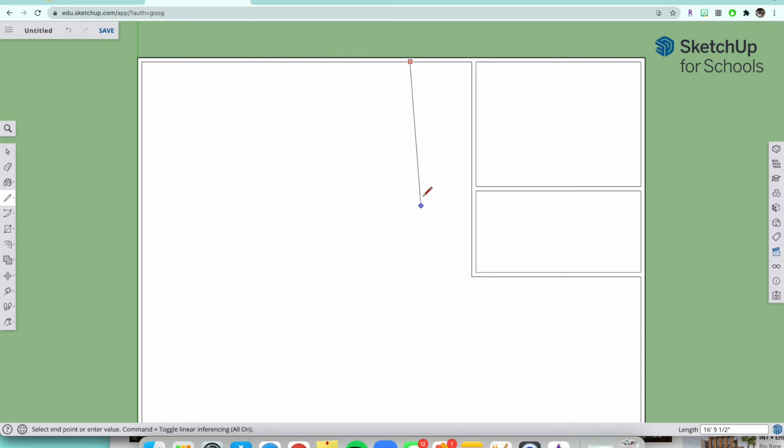All right, so I'm going to make my hallway. Let's go to the end of the rooms here, because it's the beginning of the hallway to begin those sets of rooms. So we're just going to draw a line here and click. Now you're not going to click off, you're not going to click escape, and you're going to move your cursor to the left so you can see that red line there. All right, that means it's a straight line on that axis.